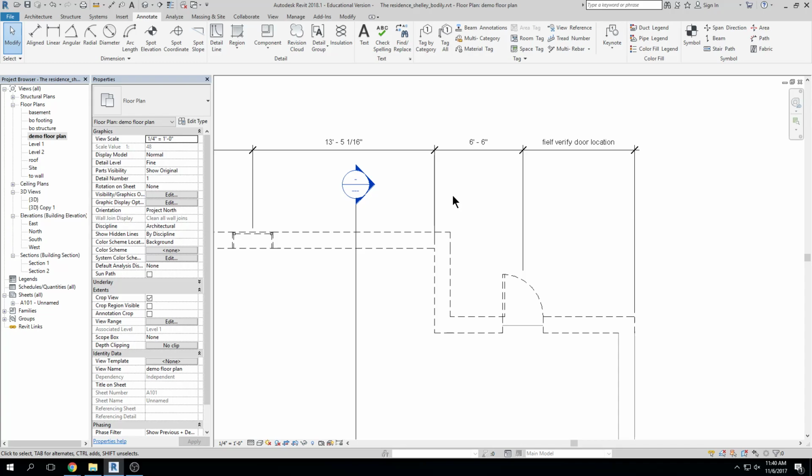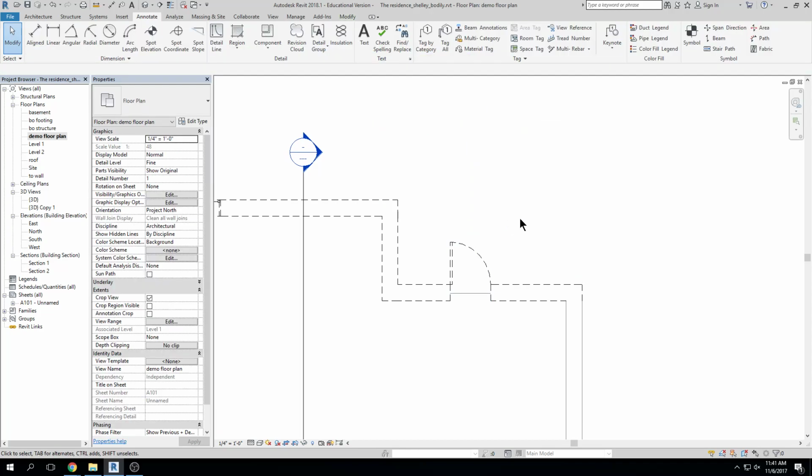If you're used to AutoCAD, in AutoCAD you more so create extra geometry to then generate the correct geometry, right? You're offsetting things, you're mirroring things about lines you generate. In Revit, you get used to creating a lot of dimensions that you then delete when you're done with them, right? So for example, I'm going to delete this string of dimensions. If I wanted this door centered about this wall, it's kind of hard. I mean, I could measure on each side. I could draw a line and then center it, but it's a simple task, but it's a little bit hard to think about doing in Revit, right?